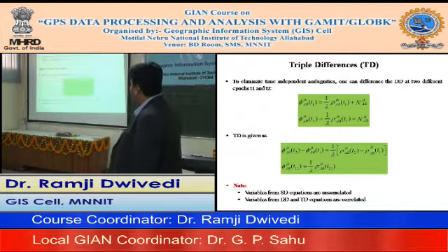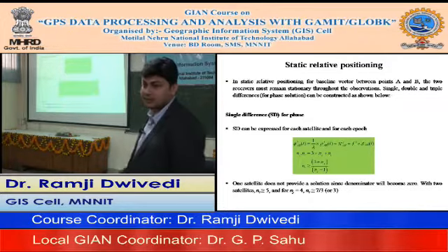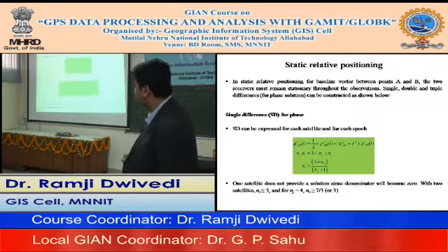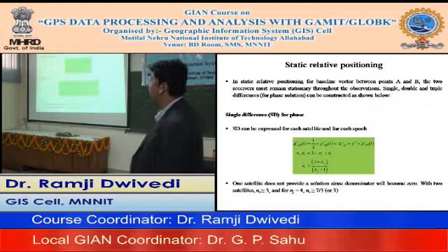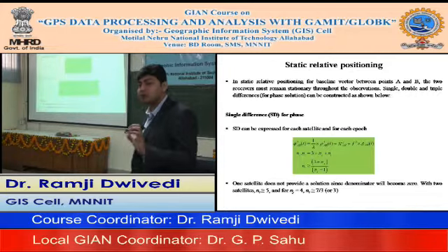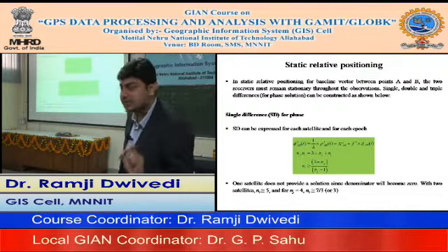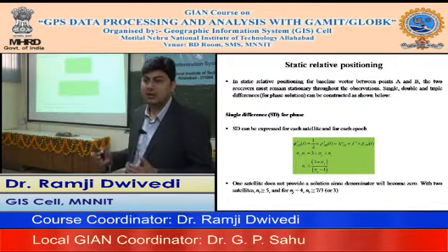Okay, so we are not going into the details of the correlation or estimating how the observables are correlated. You have single difference equations, double difference equations, and triple difference equations. The SD variables are uncorrelated. However, the DD and TD variables are correlated simply because the SD is computed from the primary carrier phases, whereas for TD and DD you actually have the single difference observable as their function.